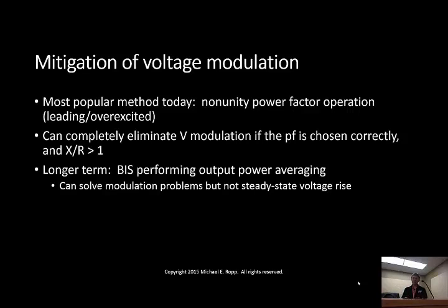Now remember, if I fix the power factor, that's the same as fixing the ratio of Q to P, the reactive power to the real power of the PV array. So what that means is that for the fixed power factor, as the real power drops as the cloud goes by, the reactive power also comes closer to zero. It's negative and coming up.